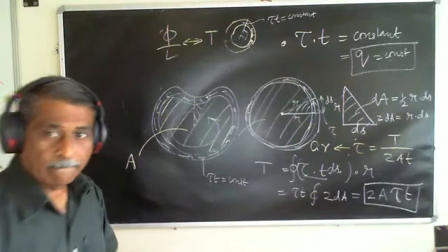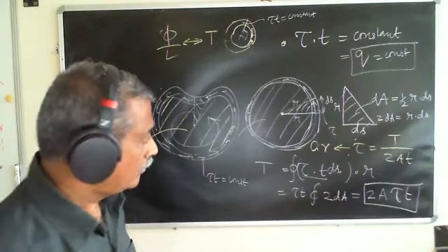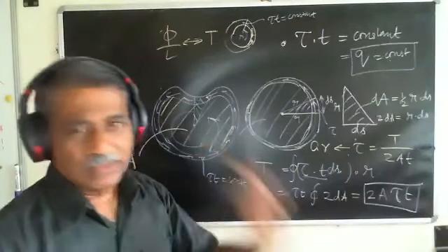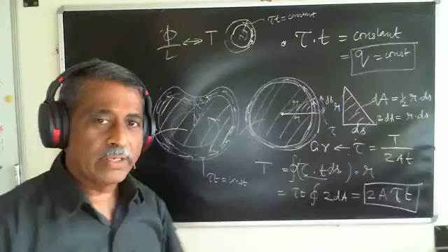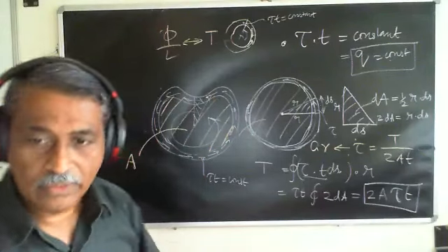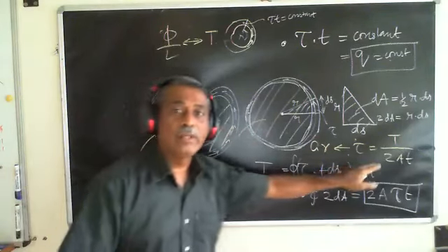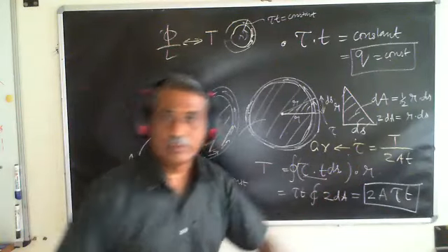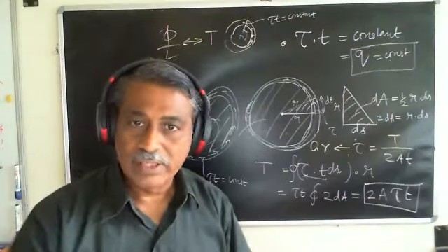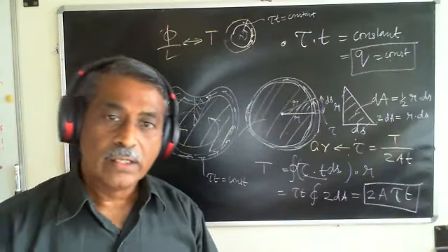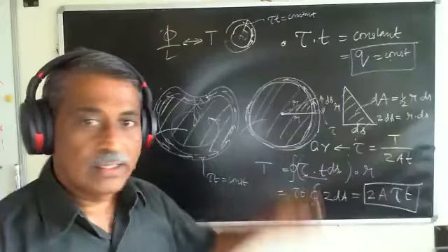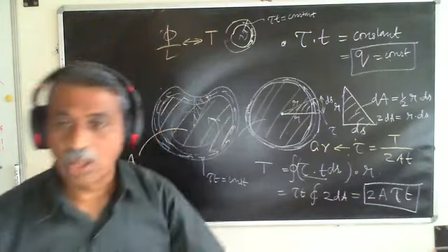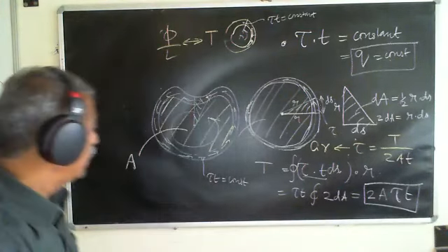Sir, we'll have to take the modulus of that because the angle can go both ways, right? Yeah, so you just take the strain energy and appropriately take whatever sign is necessary. Yes, sir, you're right. But the thing is, I already have stress, so it is possible for me to find out strain and therefore strain energy, and therefore from strain energy, using the hyperelastic understanding, it is possible for me to write down the relationship between the angle of twist and torque or twisting moment, right?